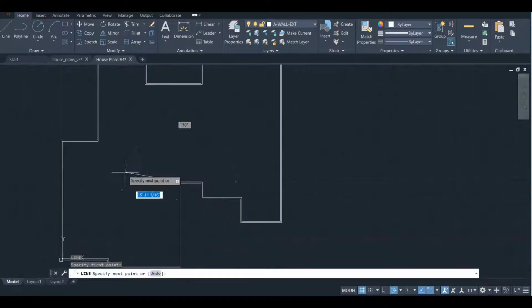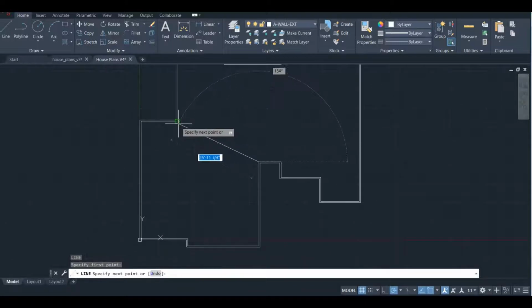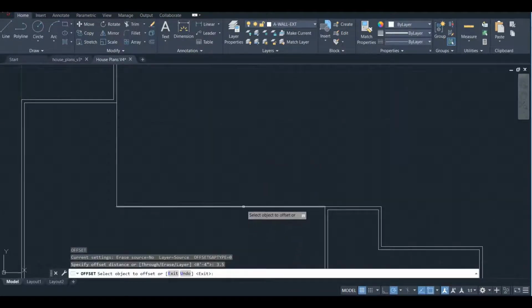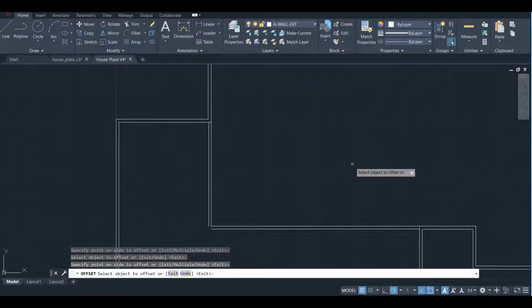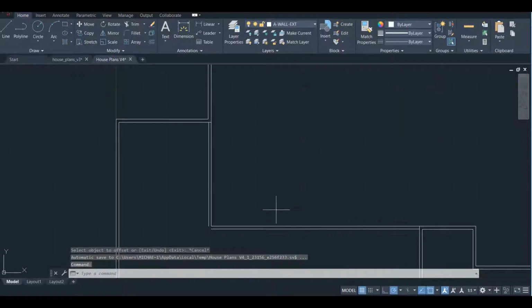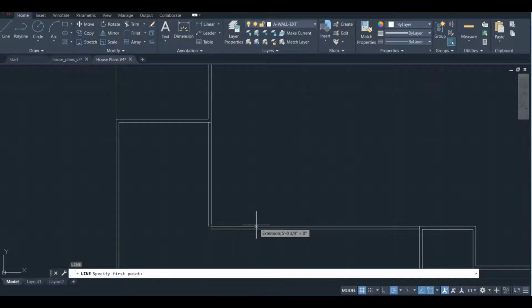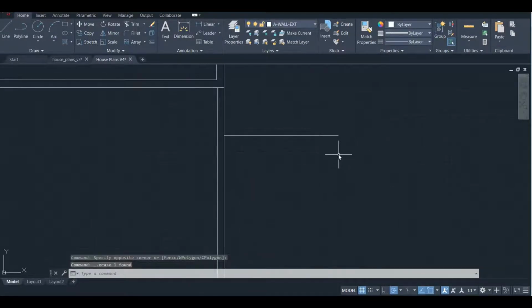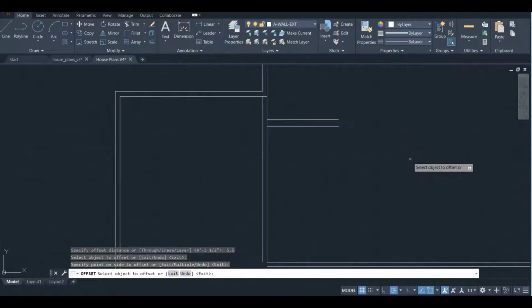Okay, this next wall lines up the interior walls, so I can reference that line. And then I can use the offset command, except for this time we have to set it to 3.5 inches. I'll come back and do that fillet later. So they're telling me it's 9 foot 3.5 inches from this wall to this wall, and then they assume a 2x6 wall, so that means I need to offset 5.5 inches, because dimensional lumber isn't actually the size that they say it is.